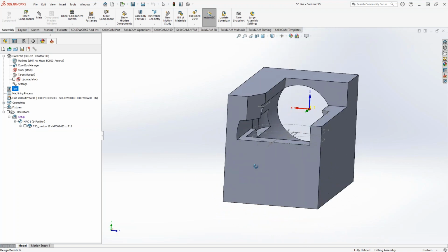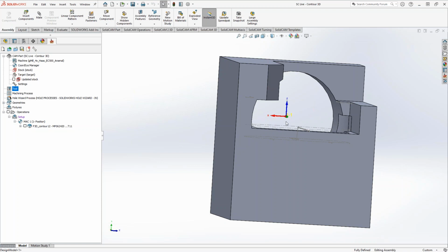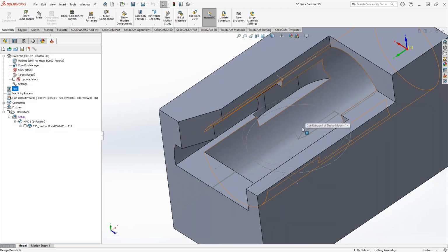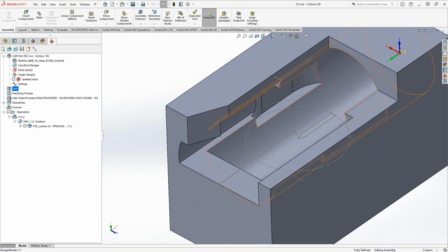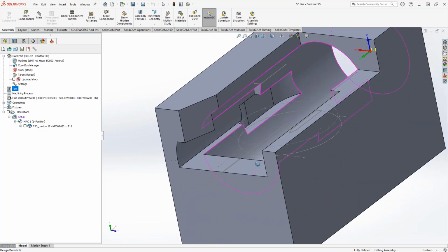So the solution was, first we mill all that out, obviously, as much as you can with whatever toolpath you have, Pocket, 3D machining. And then you cut yourself this slot so that the tool can come in, go down, machine that, and come back out the same way. Now, those sort of movements are not covered by Pocket, Profile, T-slot. Those would be what I would use if I had free access to this, but I need to control the movement of the tool to an exact movement, or else I'm going to collide with some of the side walls and the top and stuff.